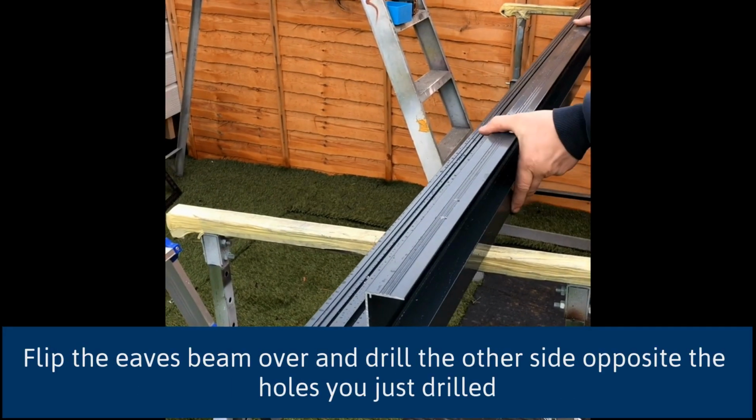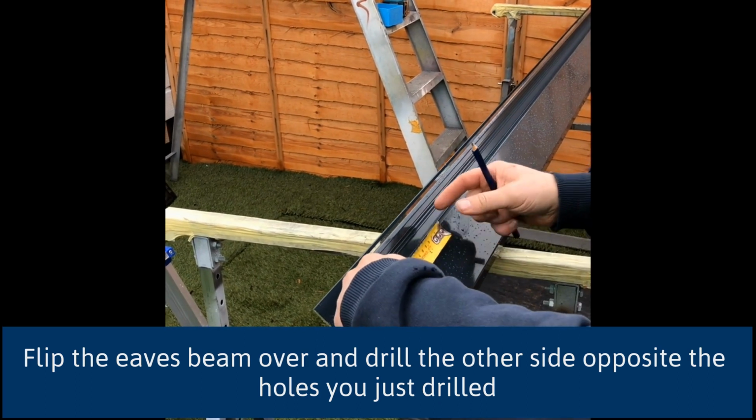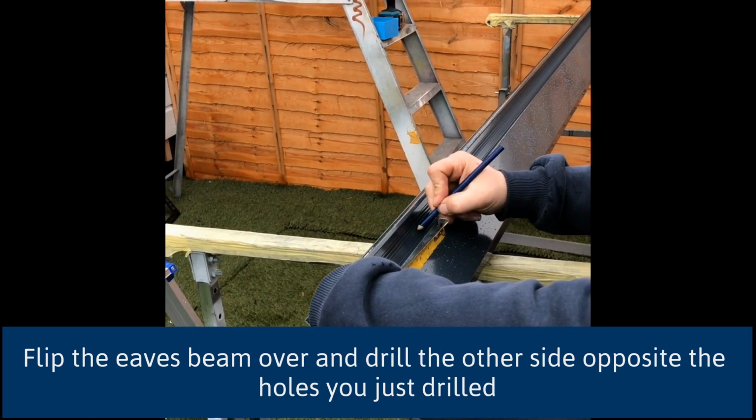Flip the eaves beam over and drill the other side opposite the 2 holes you just drilled. This will allow for the fixings to go through the eaves beam into the post.